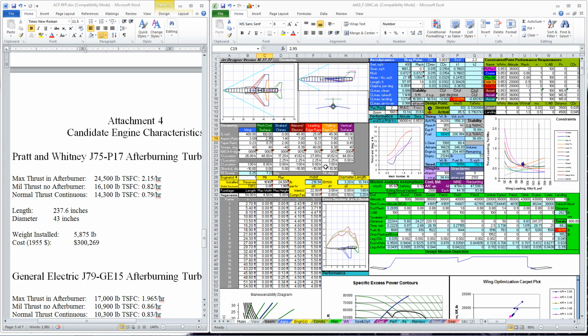Right now its Z coordinate for the pitch control surface is 8 feet. Let's make it 0. Puts it down kind of right behind the wing, but I'm not sure that wing needs all that anhedral anymore. Let's get rid of that. Let's go to 0 dihedral. That might help our CN beta. The wing was probably destabilizing a little bit. And then we can actually move the horizontal tail forward a little bit so it's got a good hold of the rear fuselage. And it's a good size.